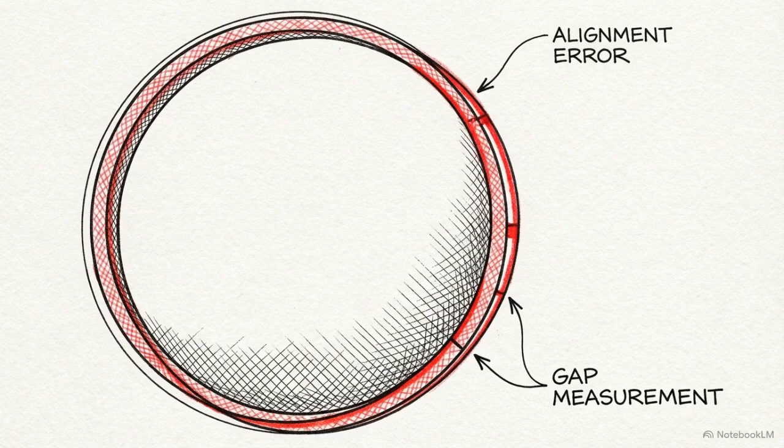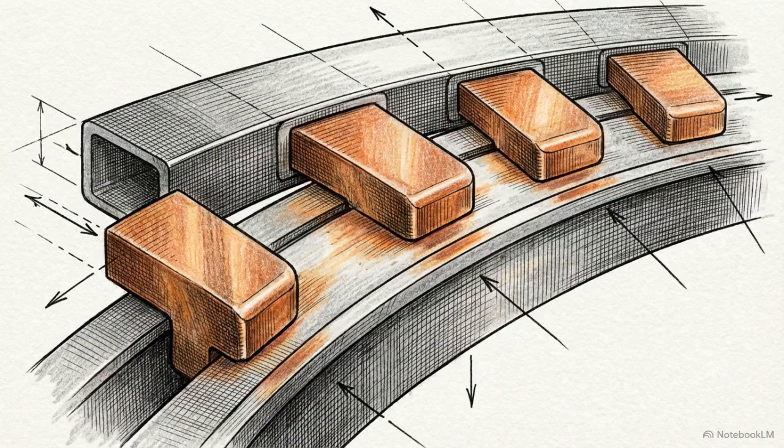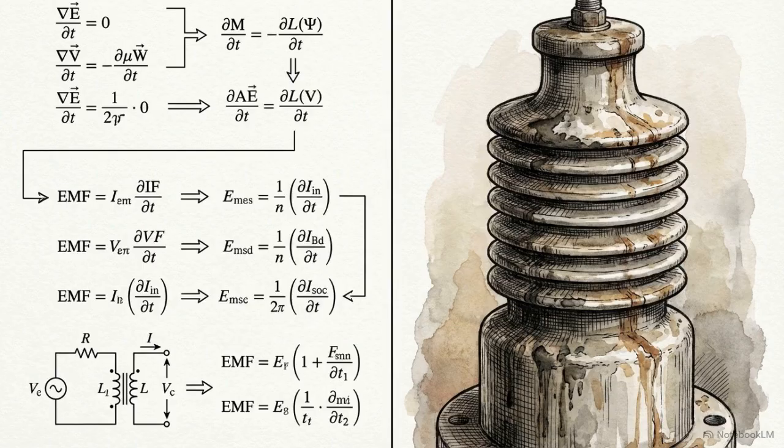Even with perfect phase and zero-sequence compensation, physical measurement errors persist. Current transformer manufacturing tolerances and the constant movement of the tap changer guarantee that the operating current is never perfectly zero. Matrix compensation aligns the theoretical math, but the relay still needs a mechanism to tolerate the unavoidable physical measurement errors of the real world.